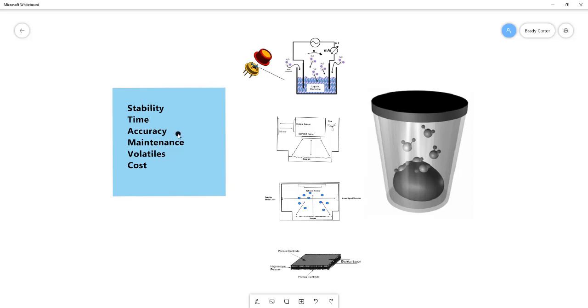In terms of accuracy and precision, which both need to be considered, the highest level of accuracy reported is for the chilled mirror or dew point sensor or method, as well as the electrolytic method at 0.003, followed by the TDL at 0.005, and then the capacitance usually around 0.01.